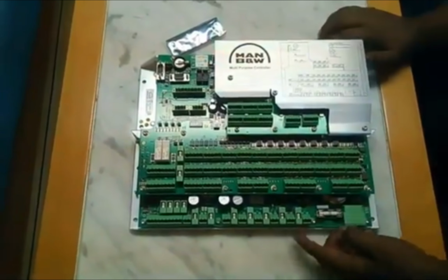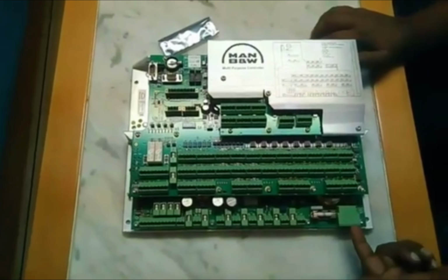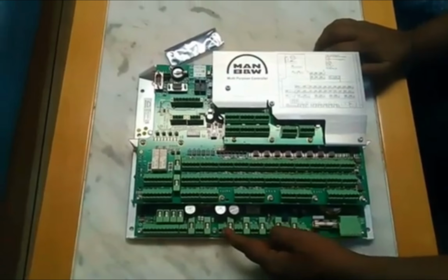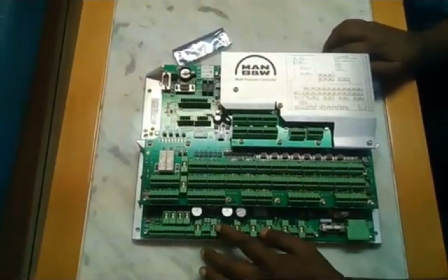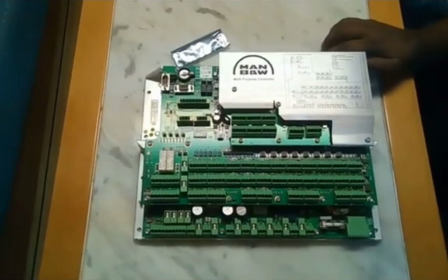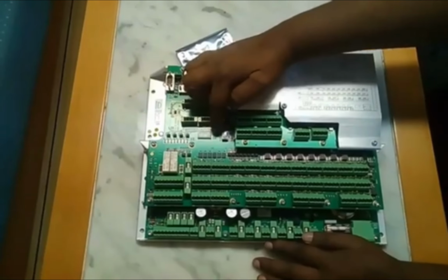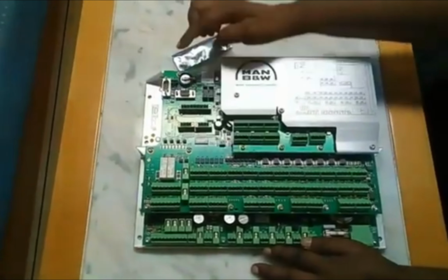This is the power filter board, and we can take the power supply from here, because this is the main input power, and main fuses are given there. If you want to operate any fuel valve, like a feeder valve or any actuator valve, you have to take the power from this source only. We cannot take the power from A and D. And when you are changing the battery, make sure the switch is in the off position.